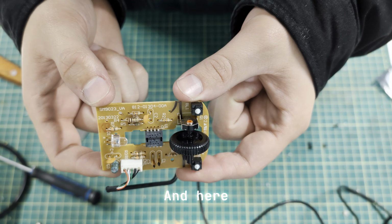And here is the mouse. If I probe the switch with my multimeter set to continuity mode, you can see that when I push the switch, all it does is short across the switch.